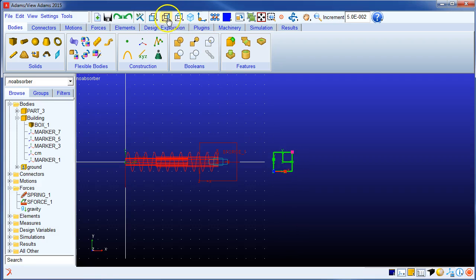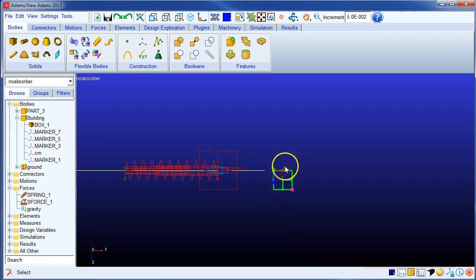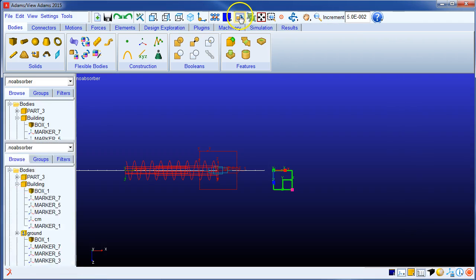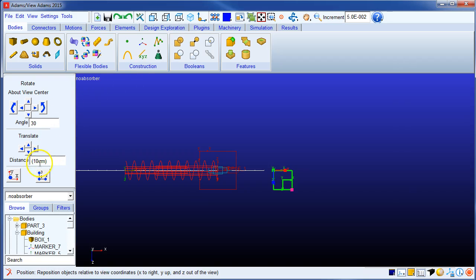Like I was saying before, look at the top view. Ooh, see, he's not really in alignment. If I were to attach a spring between the green and the building, it would be at some weird angle, and then all your calculations of deformation are going to be off, and so you really want to move him back. So what we'll do is we'll go here, and since he's 10 centimeters, I want to go halfway. I'm going to set this to be 5, and then boom, and he's back there. Okay, no problem. Let's go back to the front view.